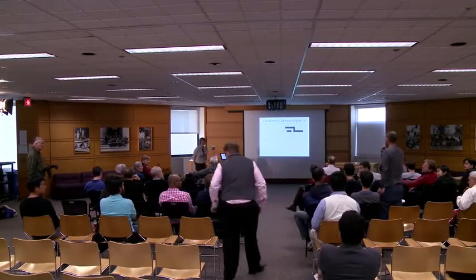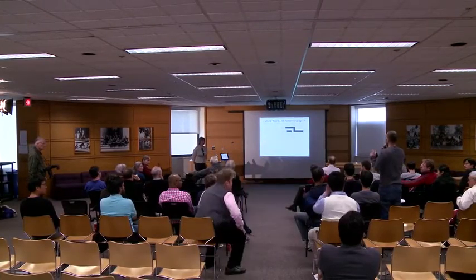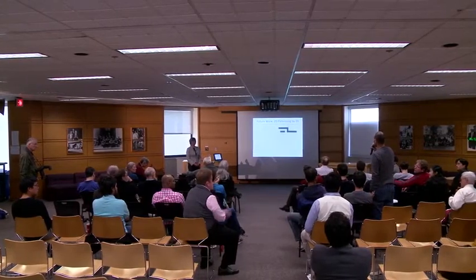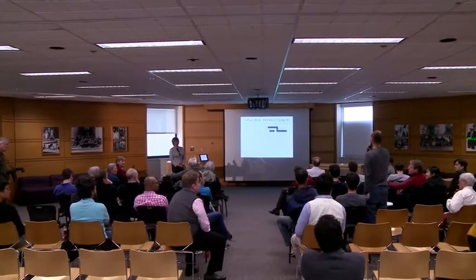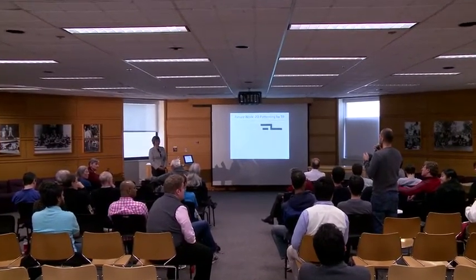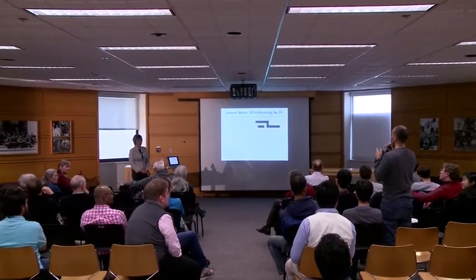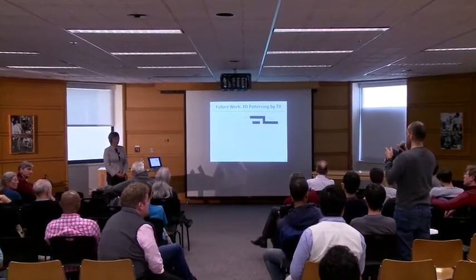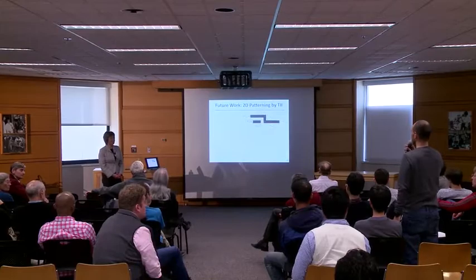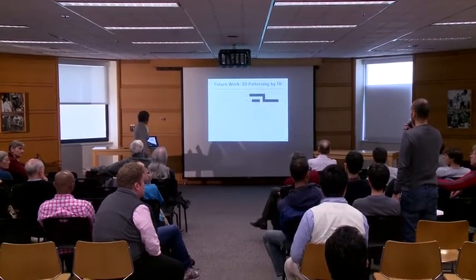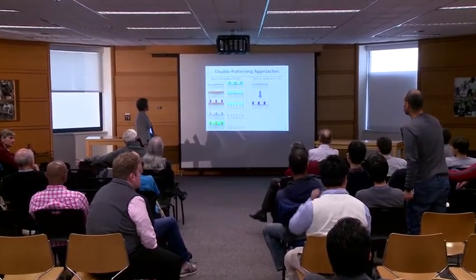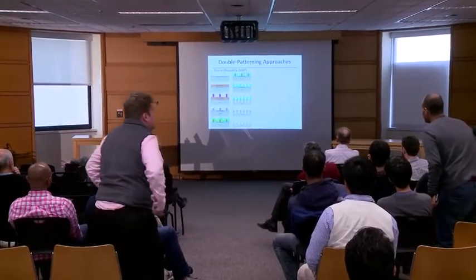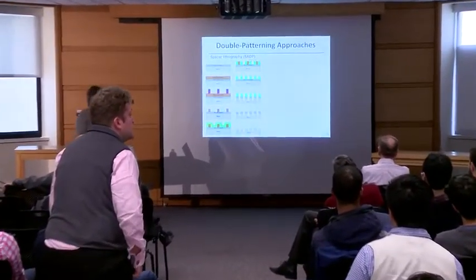Hi. Thank you for the great talk. I have also a simple question. When you are doing spacer lithography, you may have line edge roughness, but the line width roughness is very small because the edges are correlated. In this technique, the edges are not correlated. Isn't this going to be a problem? That's an excellent point.